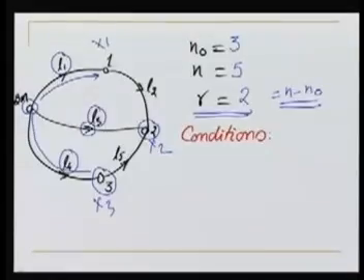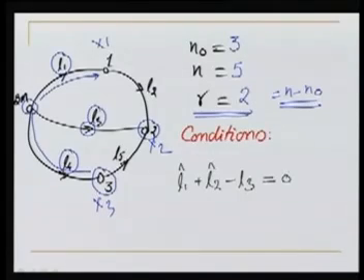And L3 is the difference in elevation between point 2 and the benchmark. It's a closed loop. So using this closed loop, we can write one condition equation, and that condition equation will look like L1 hat plus L2 hat minus L3 hat is equal to 0. Now please mind it, I have put an arrow here. That arrow shows the direction, or the positive observation.